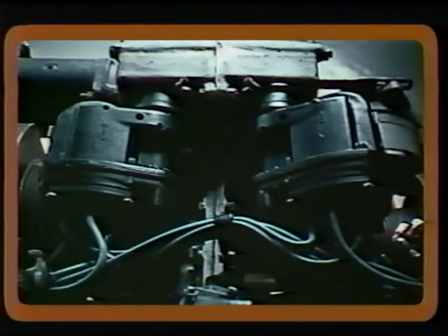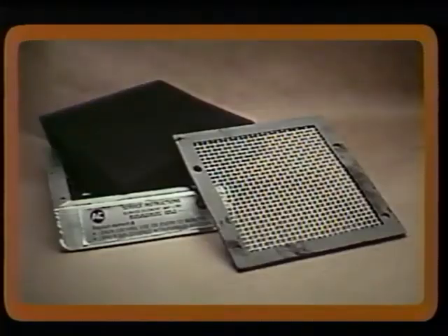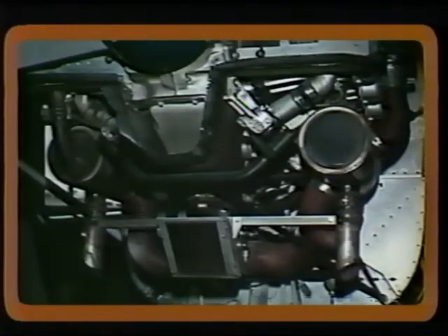Fuel metering systems are blamed for many faults for which they are not responsible. So before performing any maintenance on pressure carburetors or fuel injection systems, be sure that both ignition systems are operating properly. All of the fuel strainers are clean, and the selector valves allow maximum fuel flow. The air filters must be clean, and the muffler must not be causing any undue back pressure.